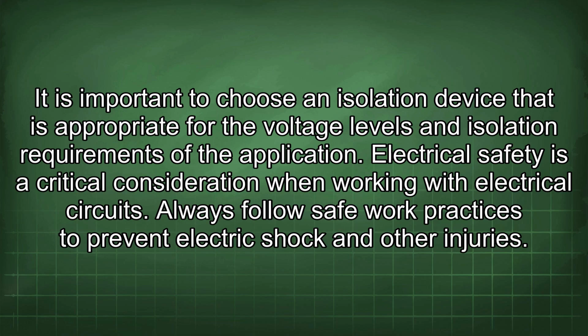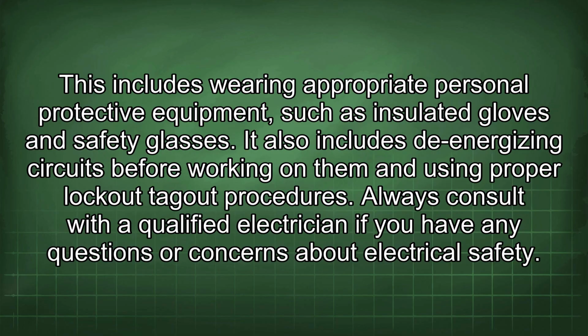Electrical safety is a critical consideration when working with electrical circuits. Always follow safe work practices to prevent electric shock and other injuries. This includes wearing appropriate personal protective equipment, such as insulated gloves and safety glasses. It also includes de-energizing circuits before working on them and using proper lockout-tagout procedures. Always consult with a qualified electrician if you have any questions or concerns about electrical safety.